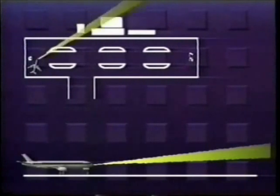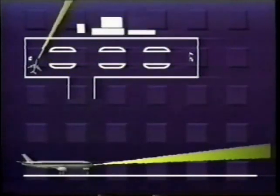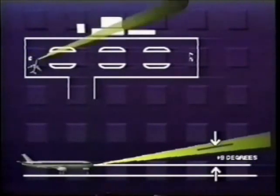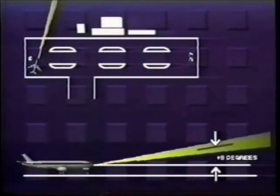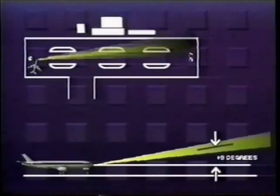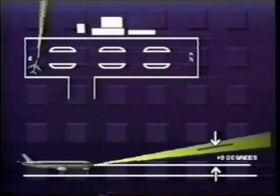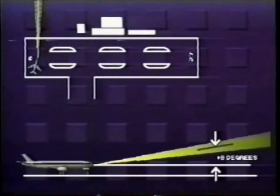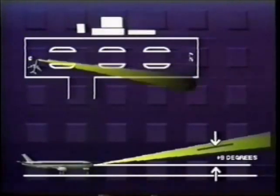This procedure ensures that components not checked previously in the test mode are working properly. With the aircraft pointed so that the antenna can scan the intended departure area, scan that volume of space by slowly rotating the antenna tilt controls to +9 degrees while looking for convective weather. If the 10 nautical mile range is clear, repeat the operation for the 20 and 40 nautical mile ranges. Look for dangerous storm shapes while being particularly sensitive to crescent-shaped storms. Remember, crescent-shaped storms are likely to be hiding dangerous weather.